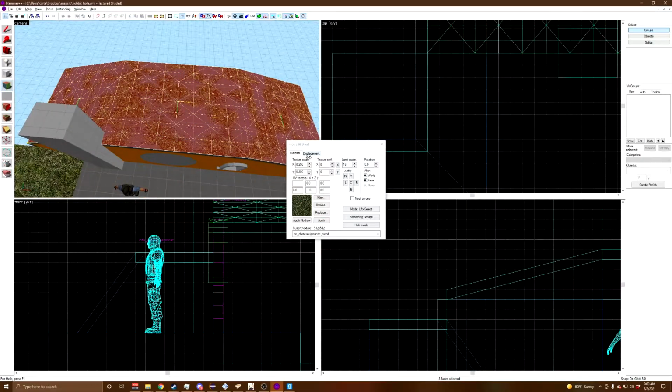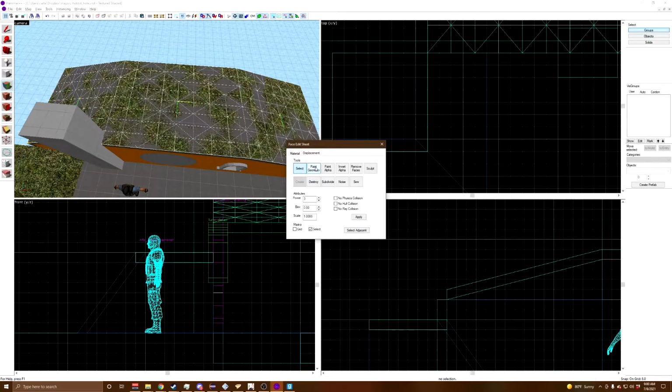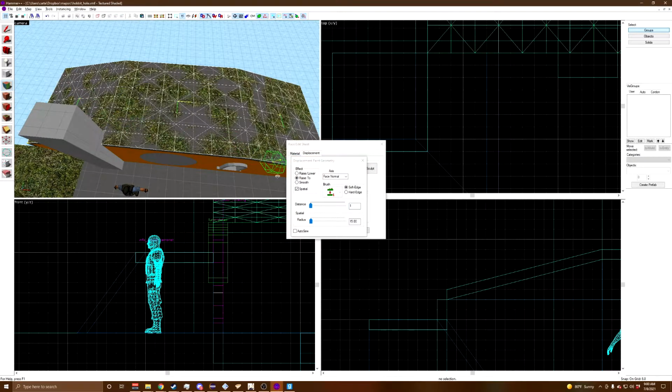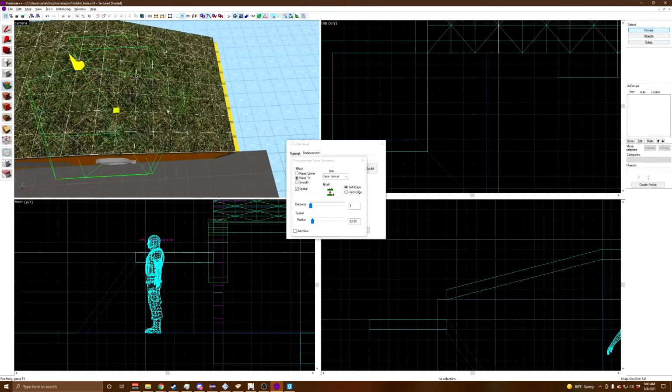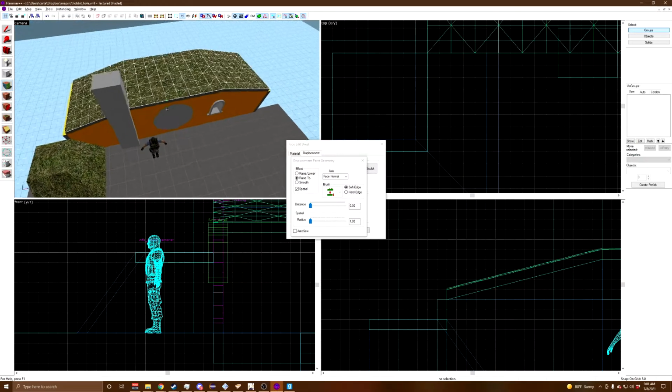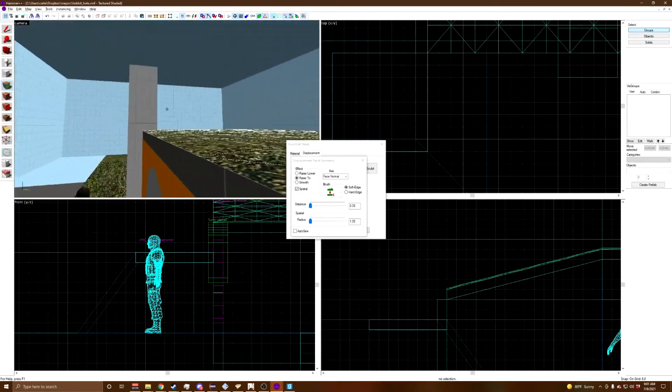You should see a ton of Z-fighting between the blend texture and the roof. To fix this, we're going to go edit the displacements by painting their geometry. Set the paint setting to raise 2 and set the value to 1. Then paint those displacements until none of them are Z-fighting with the roof anymore. Then set the value from 1 to 0 and quickly go along the edge of the house to make sure that there's no gap between the displacements and the roof.